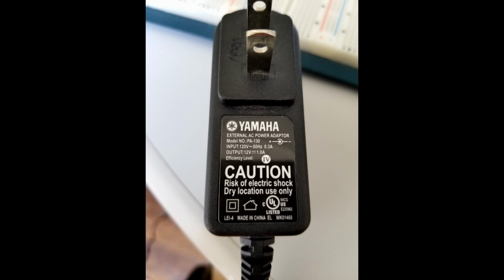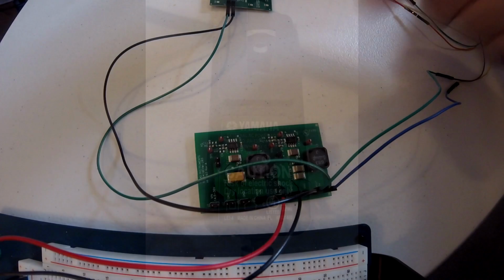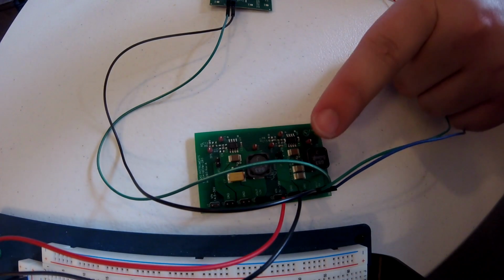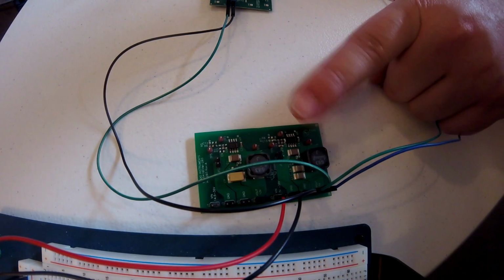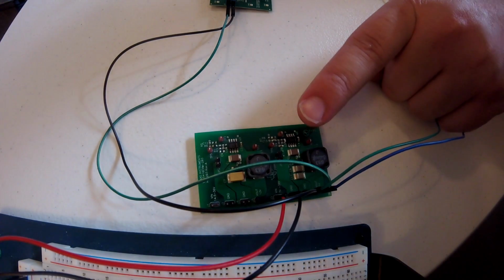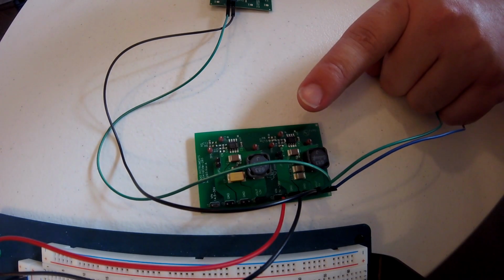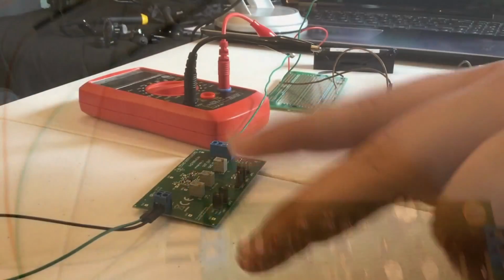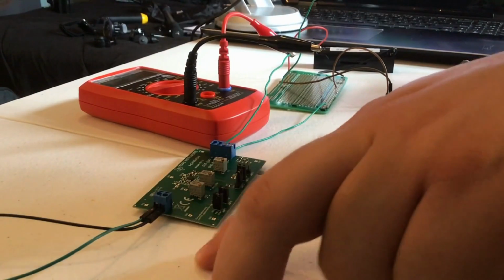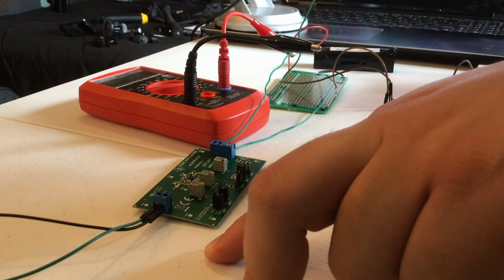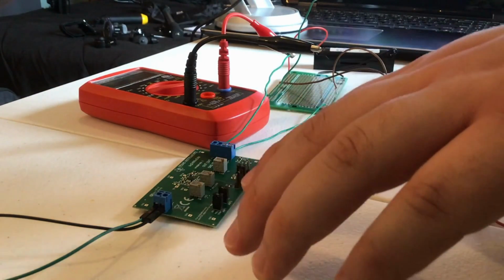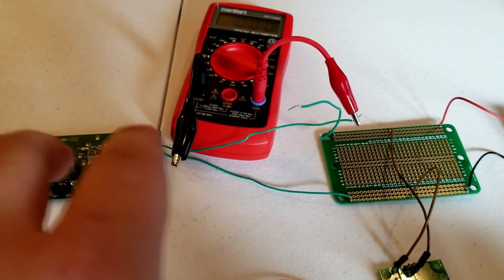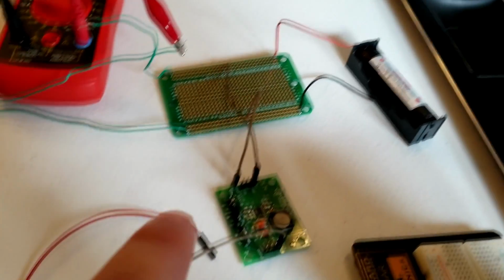So I'm using a 12-volt DC adapter at 1 amp to power this buck converter here. This buck converter is stepping down that 12 volts at 1 amp to a 5-volt signal at 1 amp. So basically, the buck converter takes that 5-volt signal and puts it into one input of this power mux. Path B is also running in parallel to that other path A. 5 volts is going into this eval module, which is then charging the battery, which is then discharging.